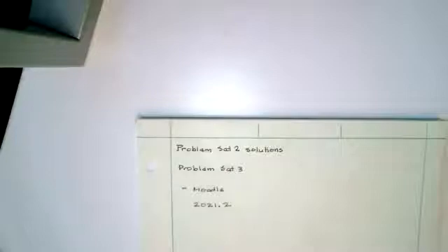There's one example, example 4, which is a derivation of 2D elasticity for an axisymmetric problem. No, you're not going to have to do 2D elasticity. The results for that example would be quite general. So essentially, that's a stress concentration factor of 2 all the way around the hole. So that's examinable, but doing something like that, no, you haven't had enough experience to do 2D stress analysis. But everything else is fair game. Are there any questions?